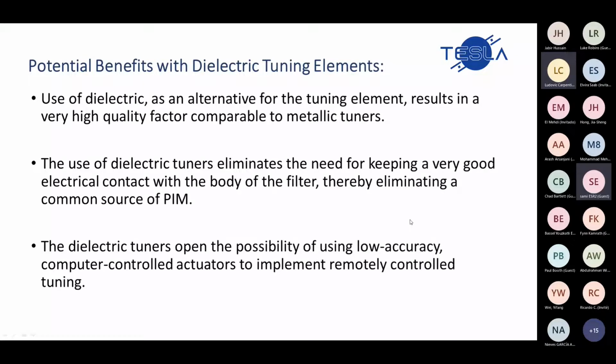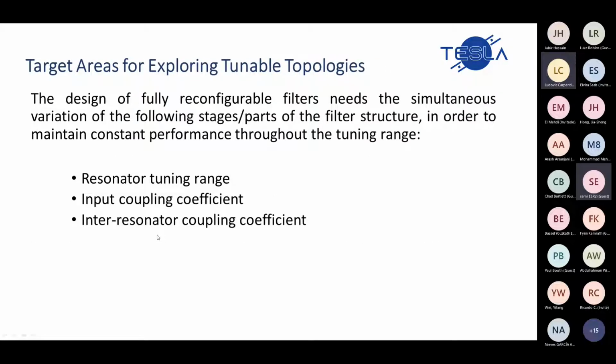There are some potential benefits of dielectric tuning elements. We don't need regular contact of a tuner with a metallic body in order to tune a filter with dielectric tuners, which makes it very easy to operate with remotely controlled motors and with low accuracy. Apart from that, using dielectric tuners makes the structure more compact and eliminates the common source of passive intermodulation while testing the filters. So let's move to the target areas while exploring the tunable topologies.